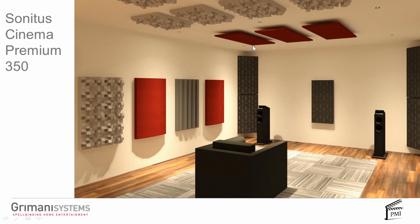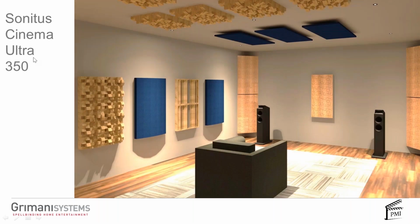I went over that really too quickly earlier, but really absorb towards the front of the room where that first reflection would otherwise bounce at your head, and then diffuse the back of the room with 3D diffusers. Right. And these could be these guys that weigh just 2 or 3 pounds, made out of hardened styrofoam. Very cool. This is our ultra solution, the expensive one, where the absorbers are thicker, the diffusers are all made out of beautiful wood. That's what it would look like.